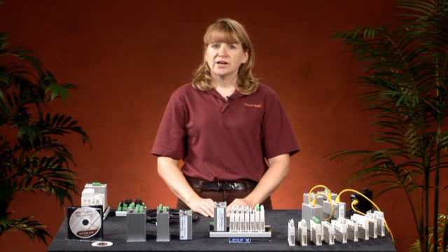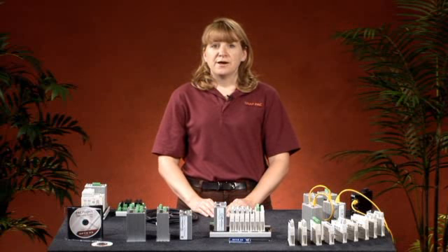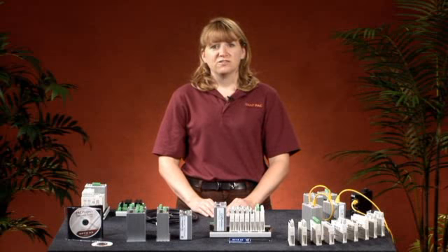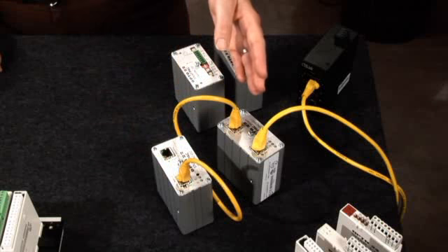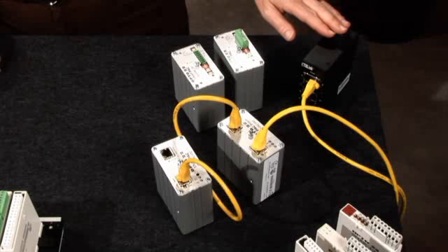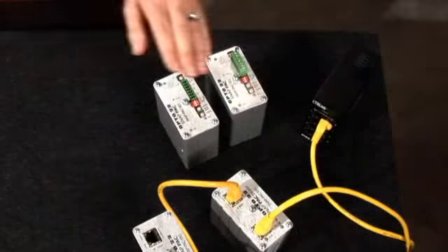And when it comes to networking your I/O, you'll love the fact that the Ethernet-based brains have a built-in Ethernet switch. That means you can multi-drop I/O units without the need for additional Ethernet switches. Or if you prefer serial networking for your remote I/O, use our SB series brains, which work on an RS-485 multi-drop network. One note, if you choose the SnapPAC R-Series controller for your application, it includes both a controller and a brain in one compact package. If your system grows, the R-Series PACs support EB series brains for additional remote I/O.